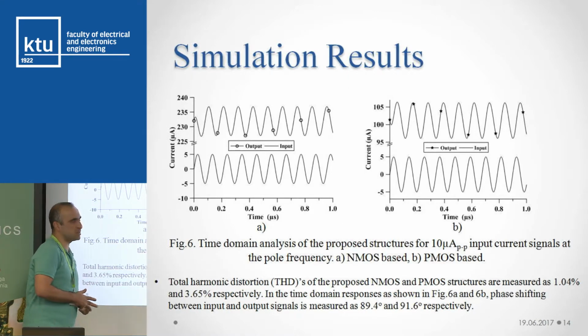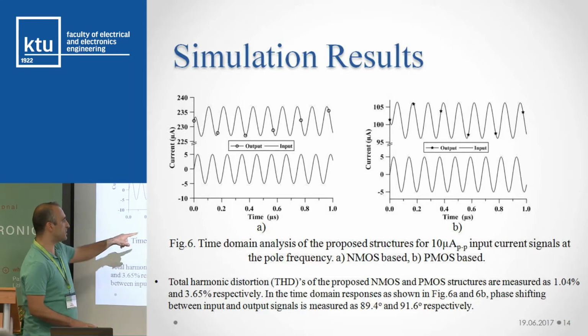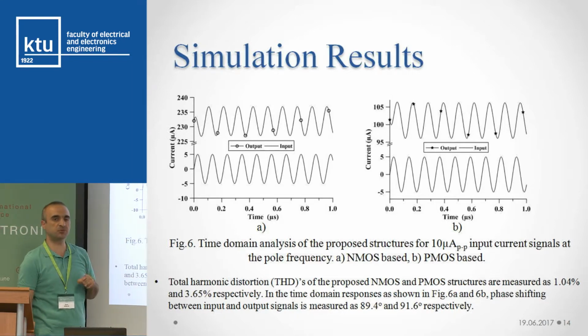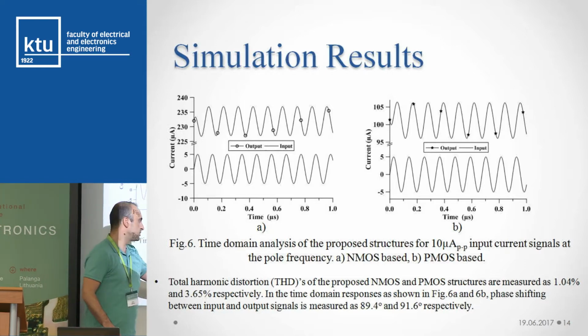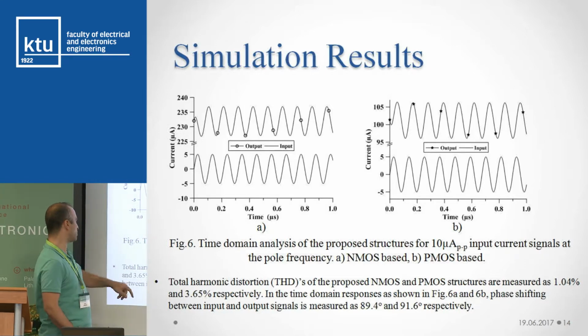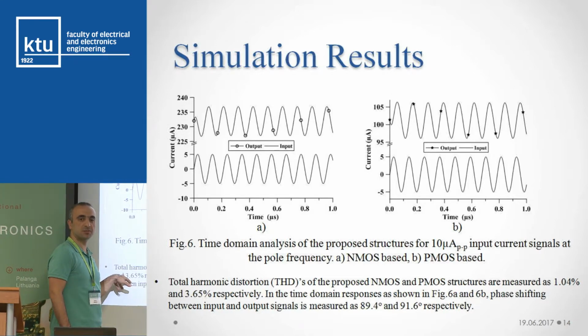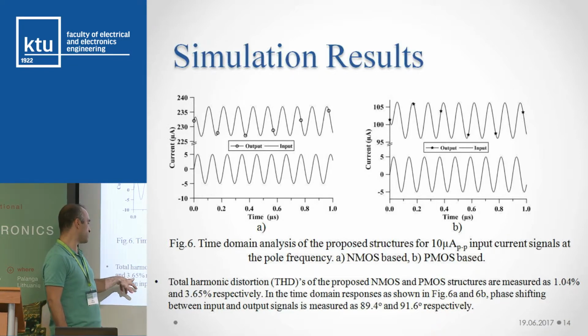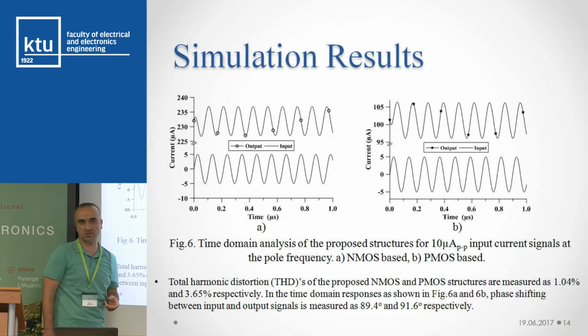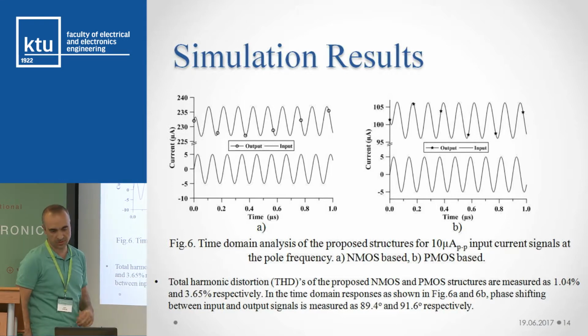Time domain simulation results. For 10 microampere peak-to-peak input value, we only have 1% total harmonic distortion for NMOS implementation and 3.6% total harmonic distortion for the PMOS implementation.